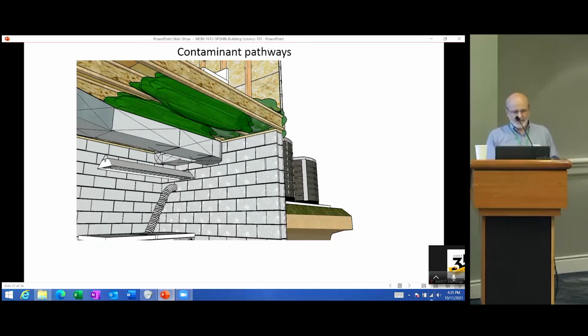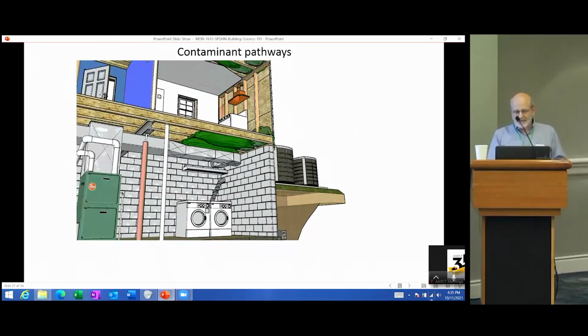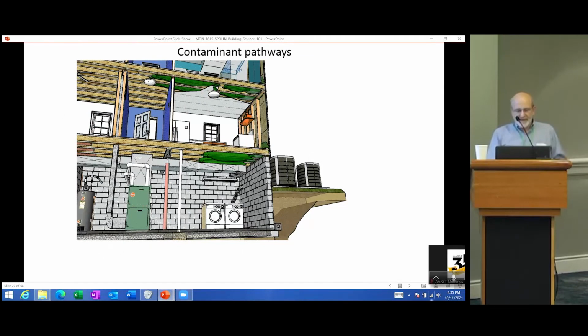And we'll go around into the basement area and see again from that band joist area. And what could be the source of negative pressure that's pulling in to the basement area could be the clothes dryer. Again, 150 to 200 CFM. That could be causing a depressurization of that space and pulling in the air from the outside, which could affect comfort, energy consumption, as well as any kind of moisture issues.